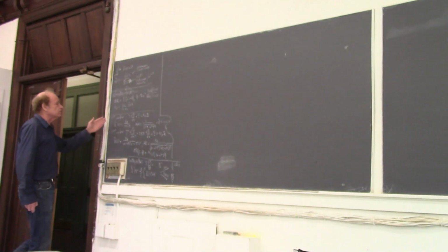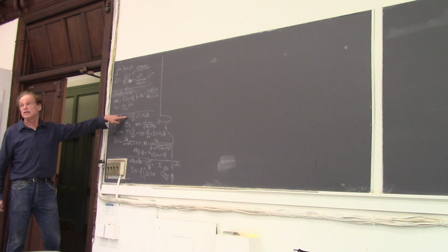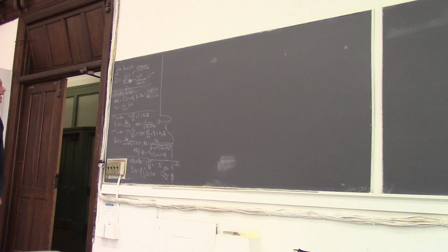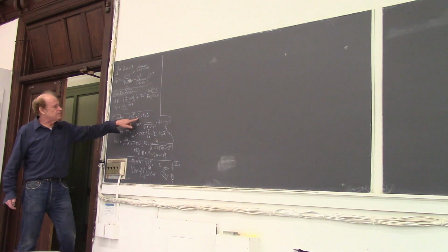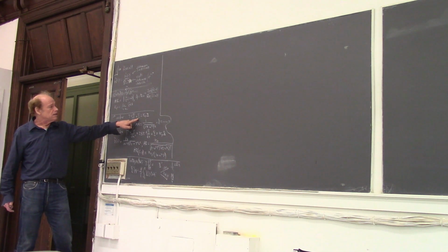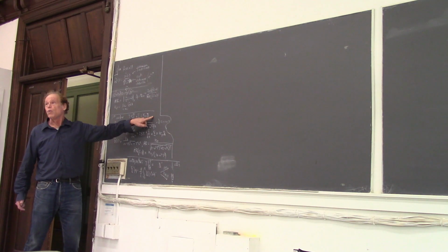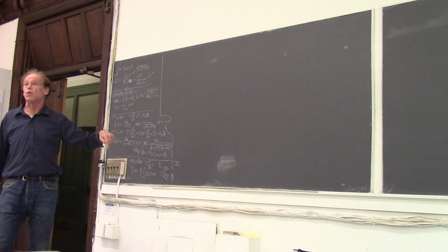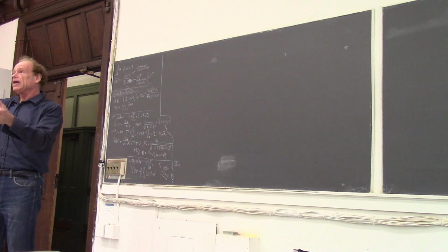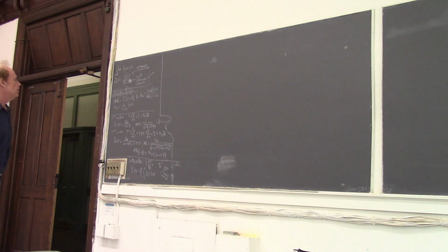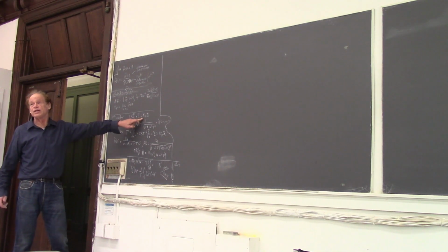So, for example, in a first order system, we found that, which looks like this, where t is a time constant and Kp is the steady state gain. And we saw in a first order system that was self-regulatory. Self-regulatory meant if we bring the y to the other side of the equation, when y gets big, then it comes in as a negative and makes dy/dt small. It brings down dy/dt. So when y gets too big, dy/dt is forced to be negative. So that's called self-regulatory. And in that case, the coefficient here is Kp.